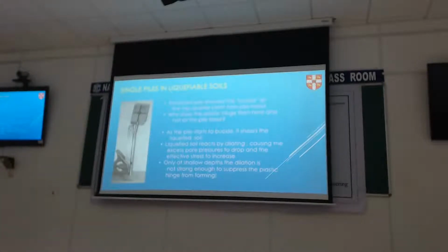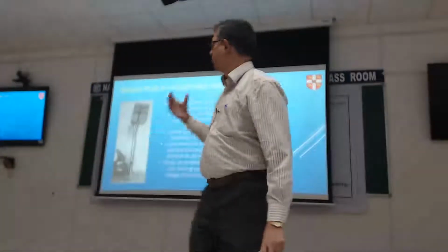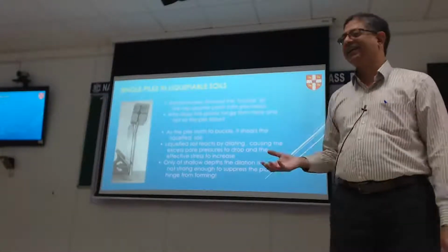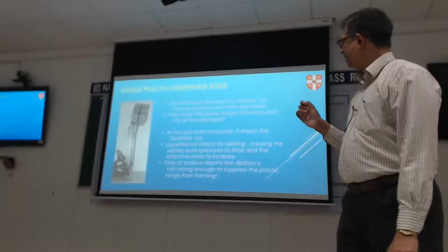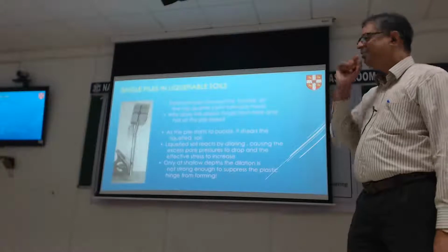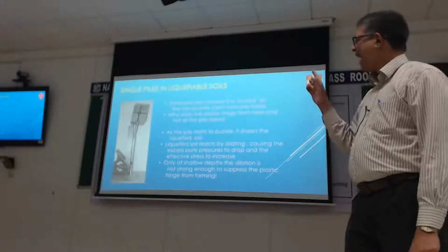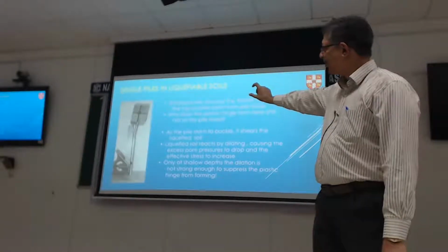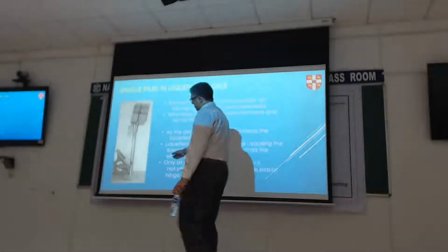And this is where me and my student fell apart. Because he said, this is proof enough that the piles are buckling, and it's a problem, to which I agree. But there's one subtle point which I wanted him to look at: how come these piles are all buckling at the top? I've shown you the other ones as well. They're all trying to buckle by forming a hinge, as you can see, almost 3/4 of the way up.